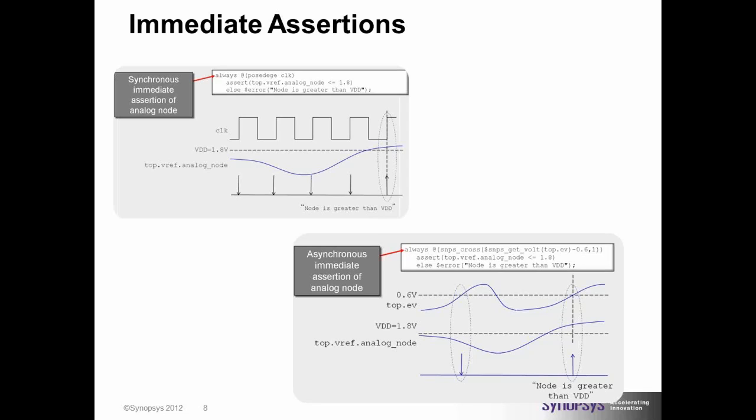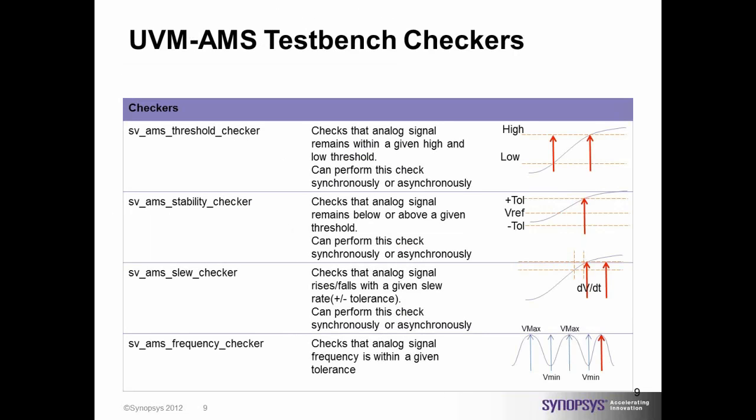Moving on to the next slide. Again, these are some of those features which I've been talking about. This talks about all the different kinds of checkers which are built in this UVM-AMS package, or SVMS package as we say, because this can be extended to any methodology, VMM or UVM per se. Some of these checkers are very interesting and they help save a lot of time. All you need to do is instantiate the checker on that particular node and provide the required arguments with them.